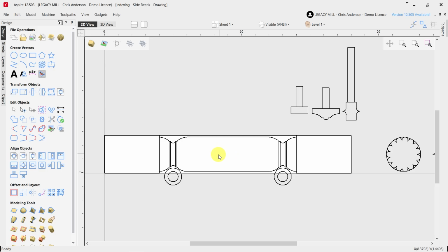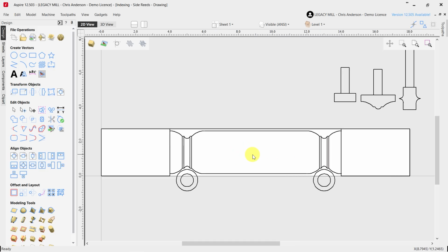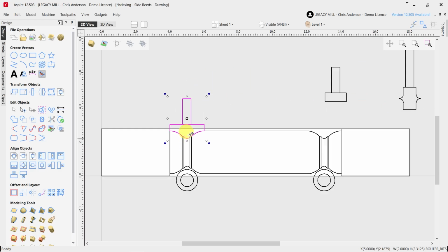Just like the other spindles, we have a square section on both ends and a round section in the center that's already been turned round on our machine. That's been done with the first two cutters. The surfacing cutter turned the stock from square to round in the center, and the 2-inch classic spiral cutter turns these profiles on either end of that turned round cylinder. That's already been programmed and cut, and if you're not familiar with the turning round and tool profile techniques, I highly recommend you check out those videos.